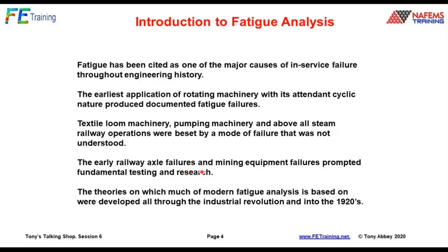So that prompted a lot of experiment, a lot of evaluation into what's going on, particularly railway axles, mining equipment, and so on. Going back to around 1840, 1860, 1870, something strange is going on. And somebody came up with the term fatigue, meaning basically the material just gets tired. They had no idea what the mechanism was, just that the material is getting tired compared to our static loading.